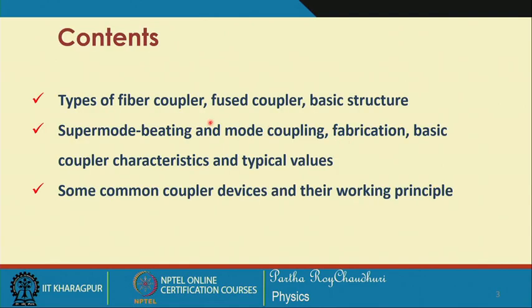There is a large variety of fiber couplers and components existing. So, we will initiate the discussion with the fiber coupler, fused coupler, basic structure, then supermode beating, that is the mechanism by which this coupling takes place, fabrication of fiber couplers, some basic coupler characteristics and typical numbers associated with these fiber couplers, and some common coupler devices and their working principle.